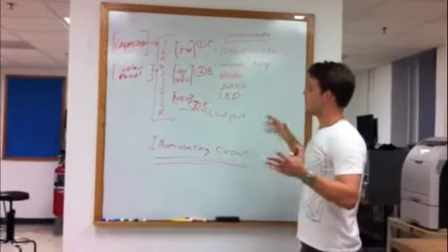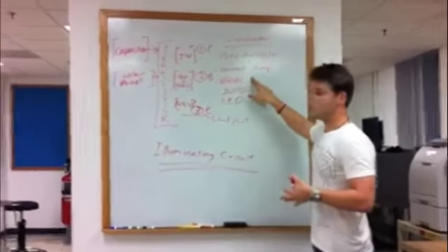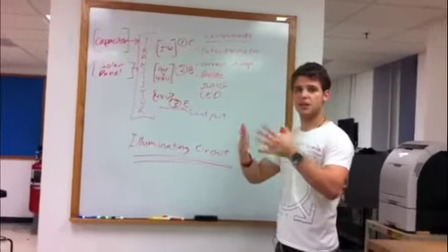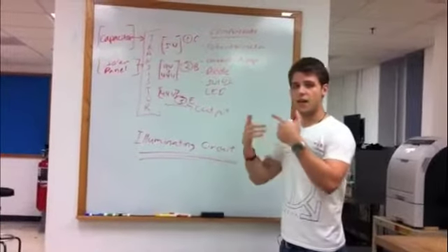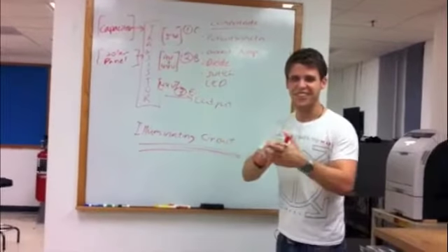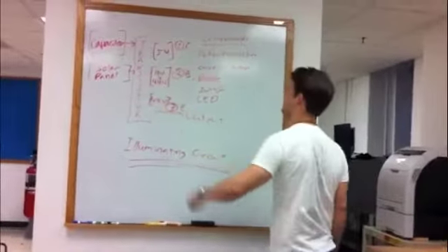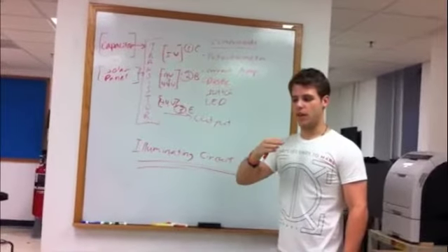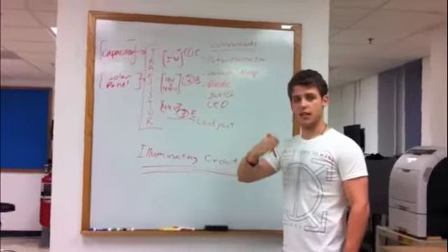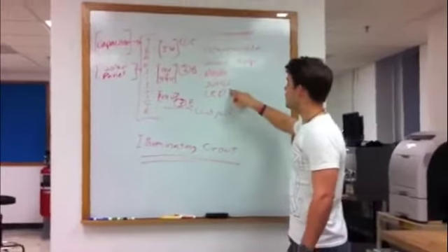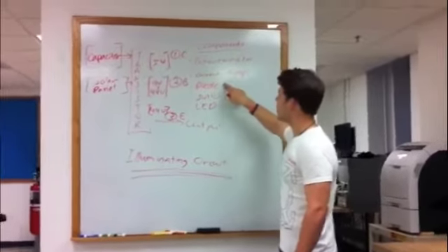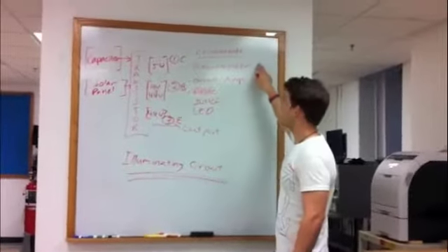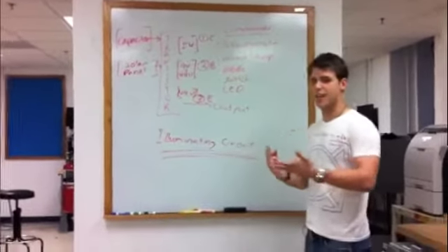Basically, we have the 5 volts running into a diode, which emits a constant 0.7 volts, which runs into the current amp and with that constant voltage, emits a also constant current. And with that current, it goes into the LED. So no matter when the capacitor is discharging, it decreases in voltage, but because of this current amplifier and the diode, the LED will not increase or decrease in how much it lights. Only if you change the potentiometer will the LED change its light.